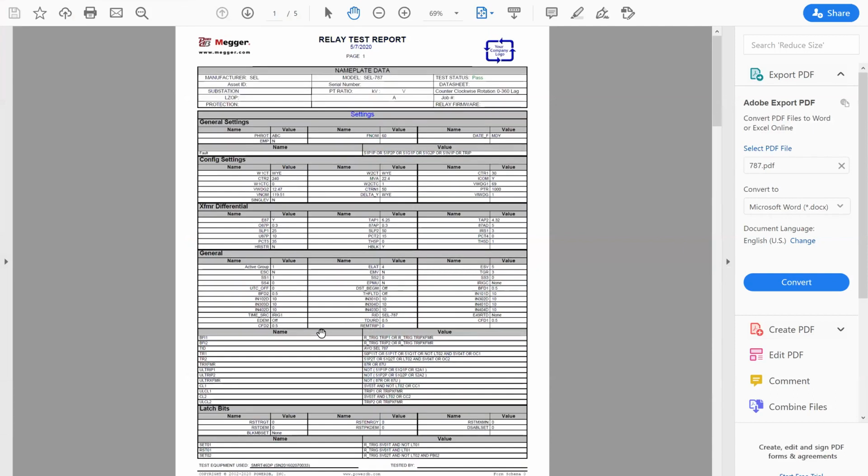Either you can do single phase by providing just one current to the neutral CT, and then connect the 3-phase CTs in a zero sequence fashion and give that to one of the currents on the test set. So you are using 2 current sources on the test set in that scenario. If you don't want to do that, you can use 3 current sources on the test set for the phase side CTs, and 1 current source for the neutral CT, and then you can define it that way.